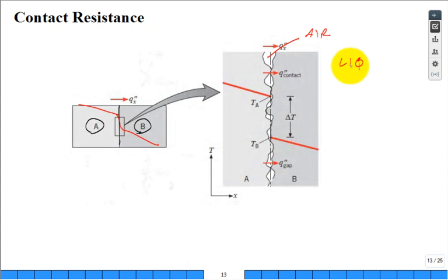Maybe you put in there some metallic material that's very soft and compliant, and when you apply pressure to push the two together, it's going to have good thermal conductivity, filling most of the interfacial gap voids. So it really depends. You could try to get some sort of metal or metallic-based grease in there to promote the heat transfer to minimize this delta T.